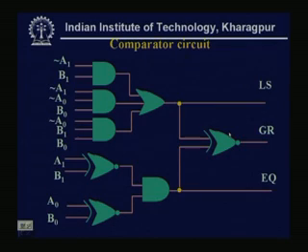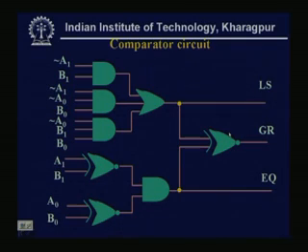So, in this way, first from the problem specification we have to set our goals, that is, what we have to determine, meaning the outputs. Then we have to identify the relation between the outputs and inputs. Then we can deduce the expressions, and using Karnaugh maps we can reduce the expression sets. Then from the reduced expressions we can realize the gates. Now, the realization can be of different types. What we have just discussed can be simple AND or XOR XNOR circuits, or a different type of realization is possible. Again we will discuss further.